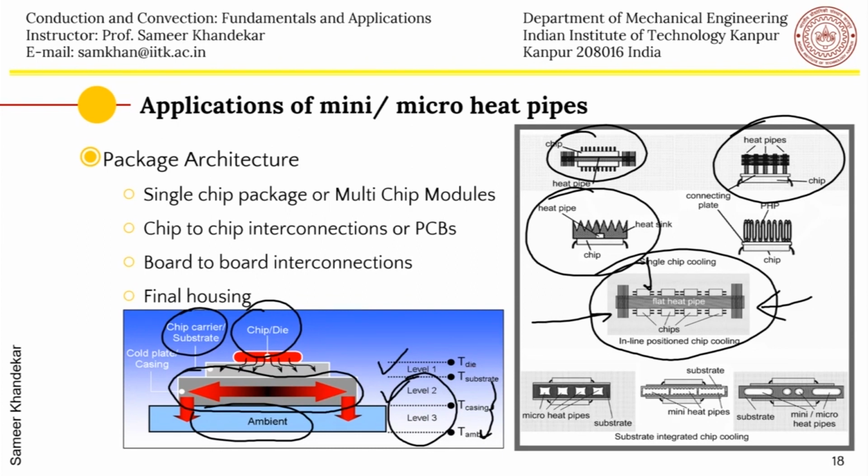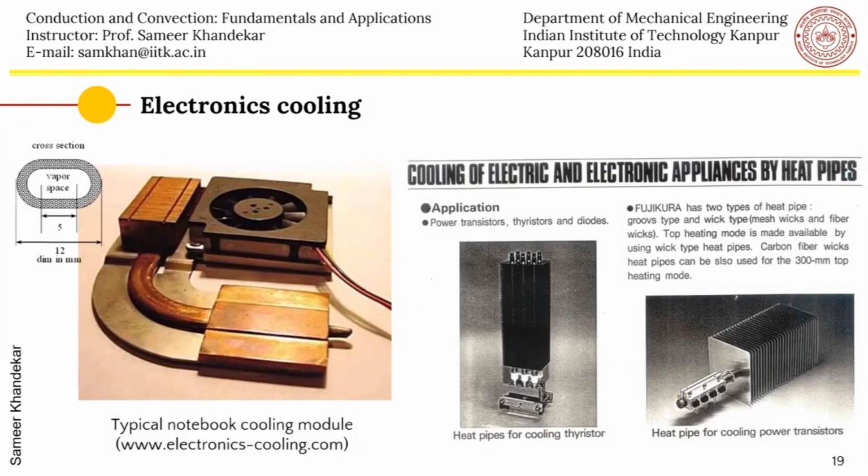Here again is the heat pipe, whose cross section can be seen here, a slightly elliptic, pressed heat pipe for notebook cooling, for laptop cooling, for example. So the microprocessor is attached here, or this particular block is attached to the microprocessor, and the heat generated from the microprocessor, of the order of 20 to 40 watts, is brought to the heat sink, where the area is very large.